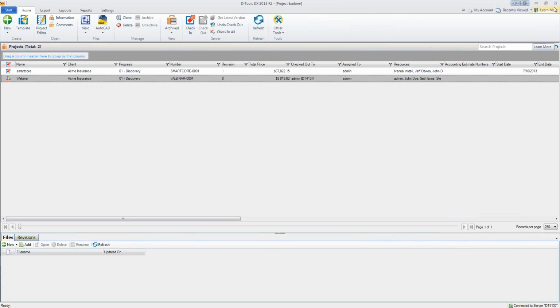Let's close this out here. Now, there's our project we've created. Now, what we're going to do next is go in and start building a drawing. Now, when you're building a drawing, you can do that in Visio and or AutoCAD. We do work with both systems equally, so you could actually use Visio and AutoCAD on the same project, and they're all linked together to the same equipment list. So if you remove equipment from an AutoCAD drawing that you've produced, it does remove it from the Visio drawing, so it is all connected.